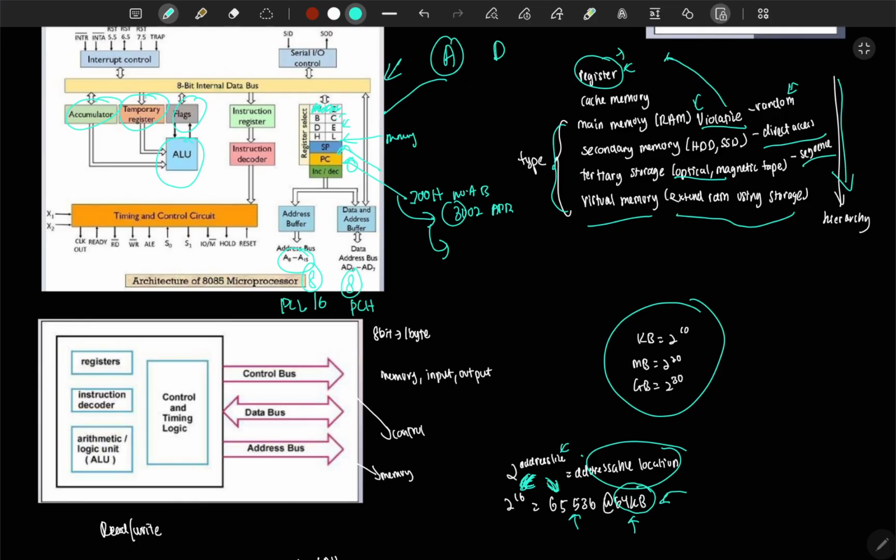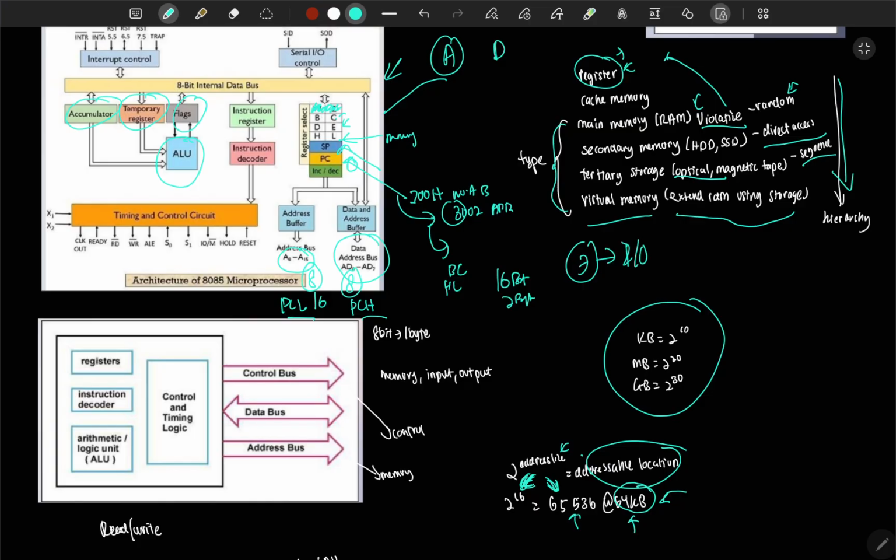Sometimes we are going to load, as I said, the B, C, D, E, H, L registers where we could input 16-bit data, or 2-byte data. The 16-bit data is pushed as the lower byte and higher byte. Meanwhile, we specifically allocate these 8 bits to IO, which is for input-output addresses. Maybe we are going to transfer data from our keyboard, our mouse, our sensor, so we exclusively reserve it for data transfer.